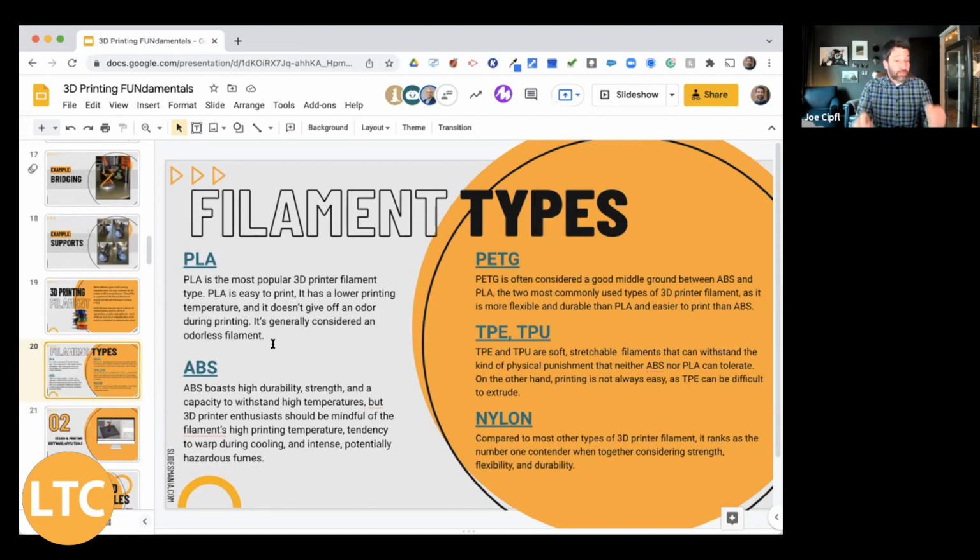Some of these steel sheets that we use on the printer beds have like non-stick coatings on them, and PETG sticks so well that it can maybe rip off that coating. So in some instances, you might put a layer of glue stick down to be a release agent to pop that print off. Other times you can take the printed object on the print bed and stick it in the freezer maybe for a minute or two to help ease it off of the print bed.